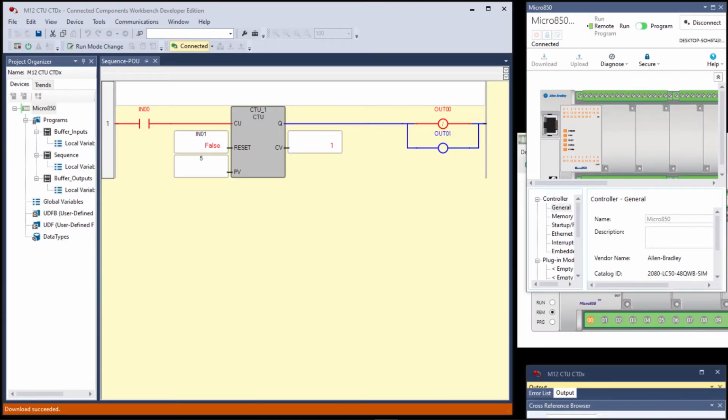Remember, our instructions in the manual were that you were to turn on input 0. If you have a live controller, then you would have flipped the switch to turn on input 0. With the simulator, it should behave the same way as a real controller. So before you downloaded, you made sure that input 0 was on and all others were off. We downloaded and the logic comes up, and as you would expect, input 0 is on.